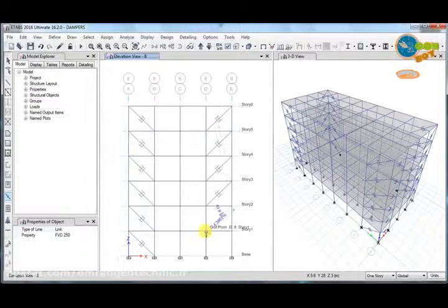Mostly in new practices where you need to provide a tall building in a small area, and you have a seismic zone, you can provide dampers to resist the building from collapse. This also reduces the deflections of the building in the lateral direction. So like this you can provide the dampers to the building.